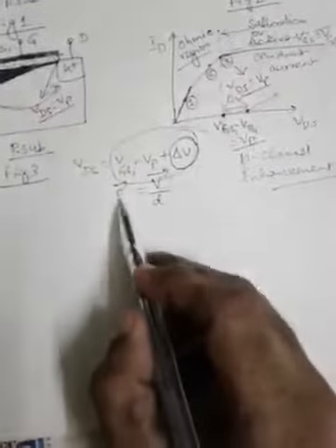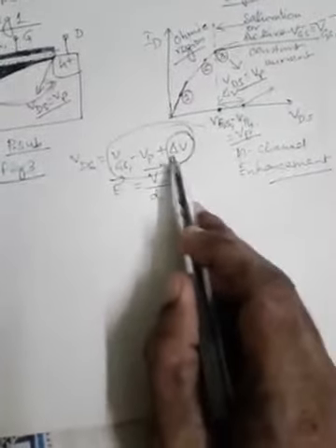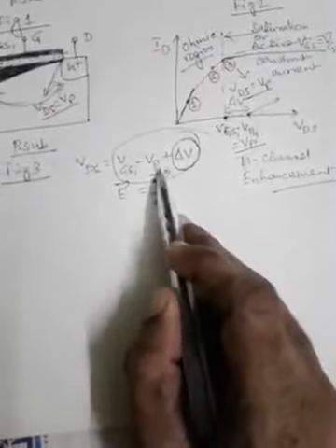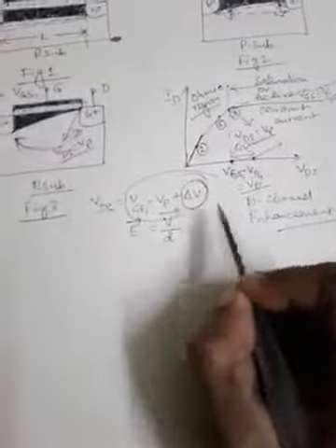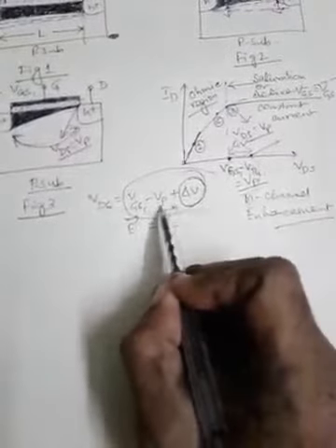So the electric field between source and drain terminals will be proportional to this total voltage, applied over the length L of the channel. Initially, when delta V was not there, VGS1 minus VP was proportional to the length, but now this additional voltage is also proportional to this length.